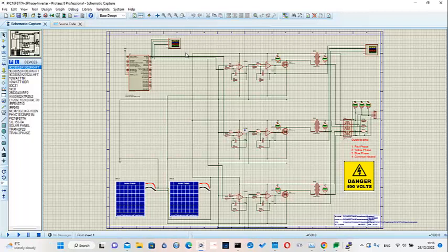We just need to convert our clock signal into a sine wave. I will not detail too much why, but there would be serious problems if I were to feed mains appliances a square wave, especially those which are inductive in nature, such as transformers or motors, and indeed, you'll see in a moment we have a transformer in this design. We need a sine wave.